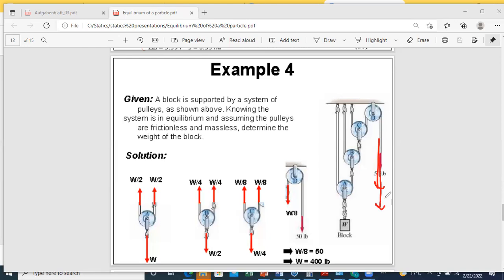If we are talking about accelerating cases, the acceleration of this point or the velocity of motion of this point will be much faster than the velocity of motion of the block, because in the end energy is conserved and power is conserved. Okay. You know that power is force times velocity. Okay, the power is conserved. If I'm imposing a certain velocity v on this part, the smaller the force, the more I can speed up. This block, because it is heavy, will move with a velocity that is lower. So from here also you can link velocities of the two using the concept of pulleys. We took the length of the cord, if you remember, and we derive it with respect to time to relate velocities of points, and we derive it again to relate acceleration of points.